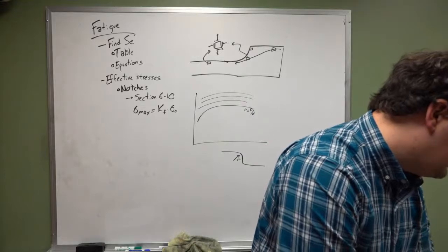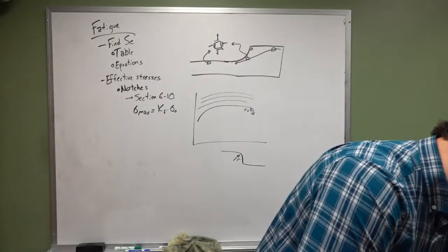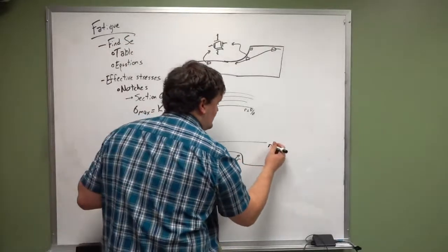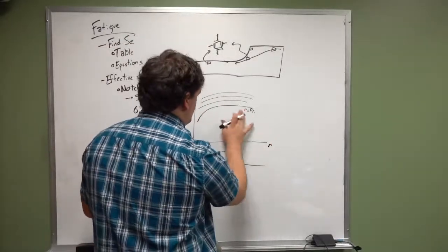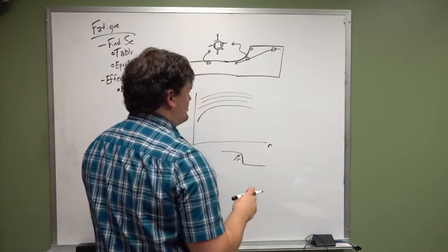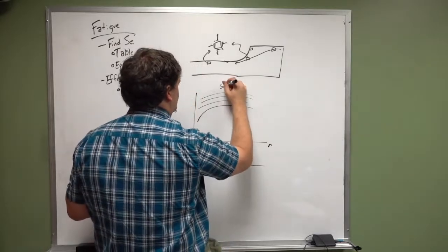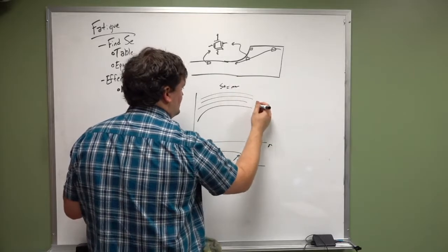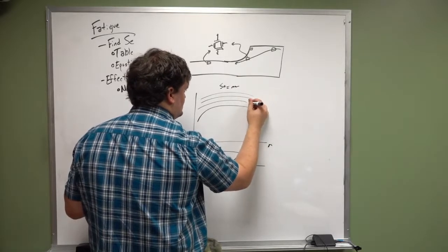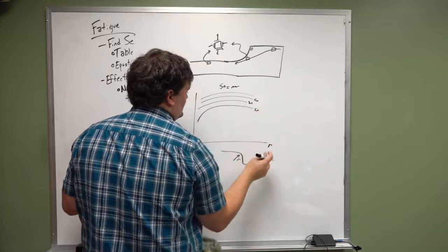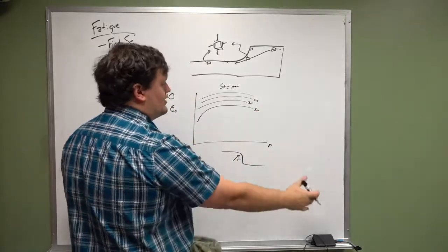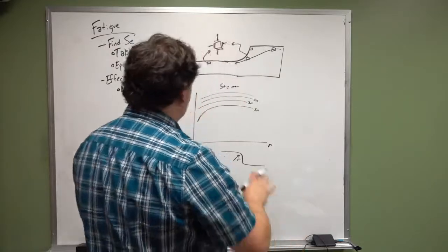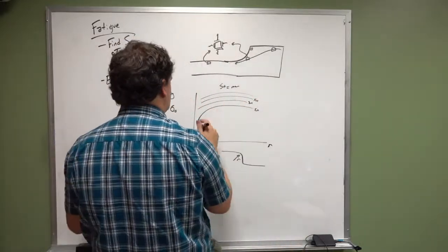I'm looking at the wrong figure. My apologies. And on the bottom here, this is then, that's wrong. The one that's given in your book is S_UT values equals some number. So this is an S_UT value, this is another one, another one. And as the notch radius grows, you see that the value slowly increases to some certain nominal value.